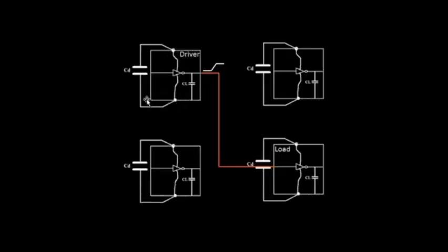Okay, for example, this was one of the macro blocks for which the problem of the current demand was solved using a decoupling capacitor. Similarly, we have this particular macro being repeated 4 times. Let's say this is your complete chip, and it has these four macros, this macro being repeated multiple times, and there is some logic present at the boundaries also.